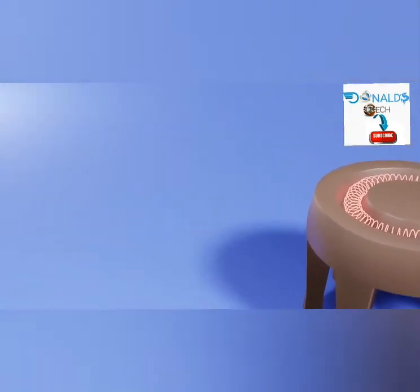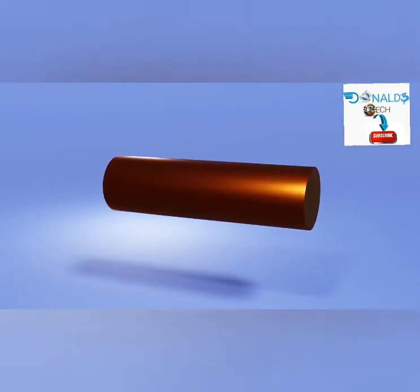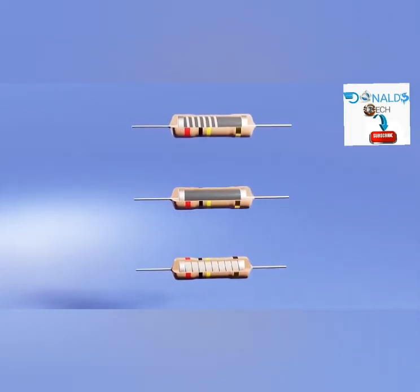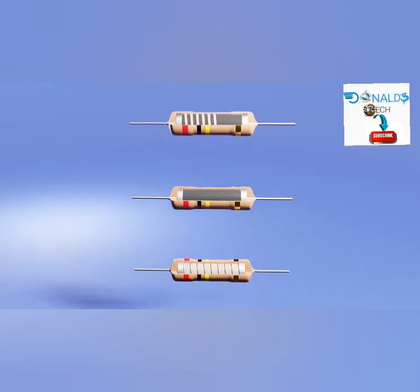in. Going back to the main topic, now that we know how to get a quantity of ohms to our liking, in theory we could create our own resistance using an extremely thin material with a high coefficient of resistance. But in reality they are not like that. If they were just a wire, it would be extremely difficult to get an accurate resistance in such a small size. There are different ways to create a resistance depending on how many ohms you want to get and how accurate its value should be.